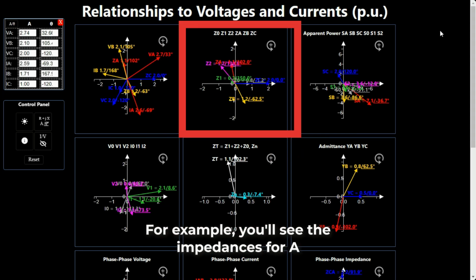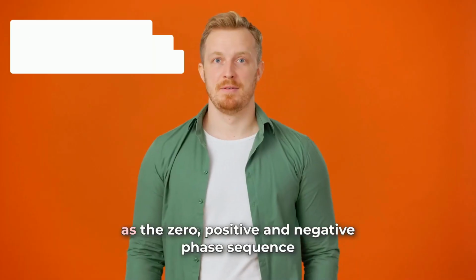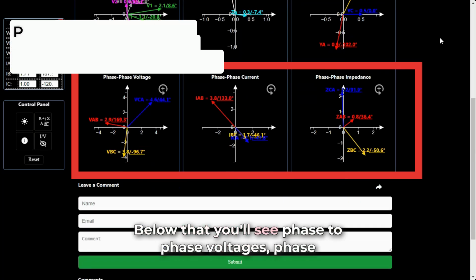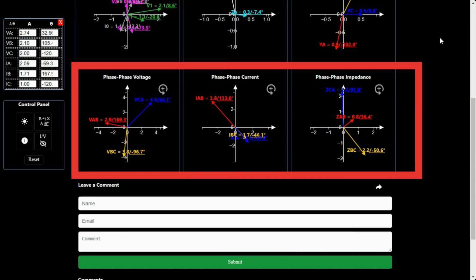Here, you have a series of pre-calculated values. For example, you'll see the impedances for A phase, B phase, and C phase, as well as the 0, positive, and negative phase sequence impedances displayed here on this graph. Below that, you'll see phase-to-phase voltages, phase-to-phase currents, and phase-to-phase impedances.